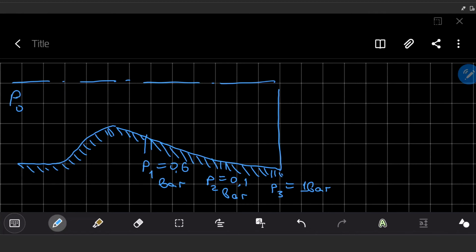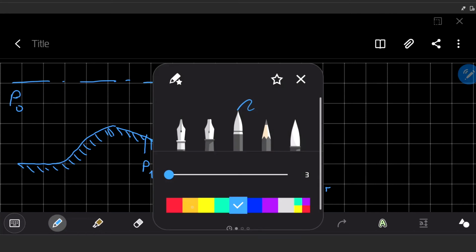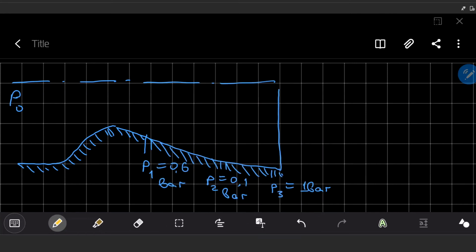How do we determine this? Quite easily: if we have a smooth geometry, we cannot have a sudden rise of pressure without anything. If we have a sudden rise of pressure, it means that the potential energy of the flow increased, and that the kinetic energy suddenly decreased, and this can happen only through a shock wave. In our case, it is a normal shock wave.